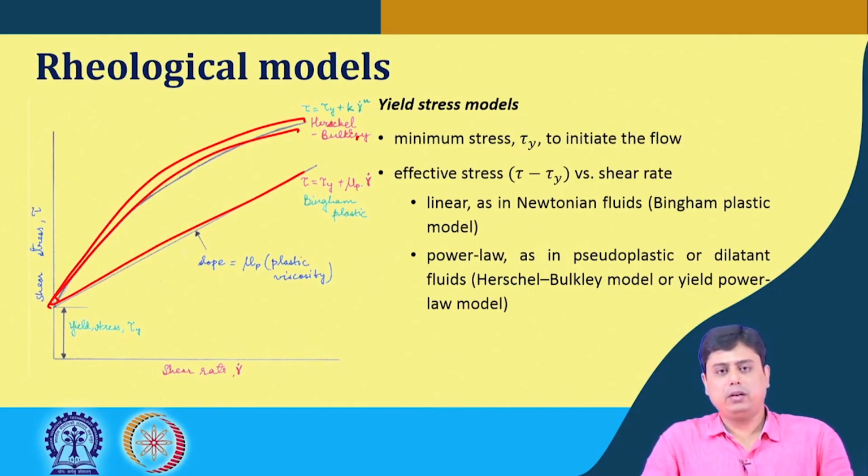From that we can detect whether the flow regime is laminar or turbulent, and depending on that we calculate the friction factor. Once it is known, we go back to the pressure drop expression, replace the friction factor and get the pressure drop. And then we started the discussion on the yield stress model, which we will continue in the next class.